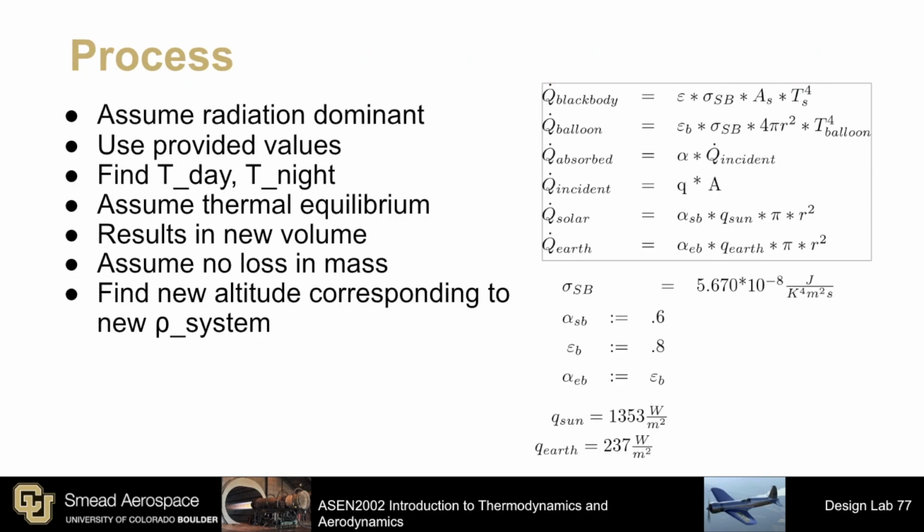Now you may be thinking that what we are assuming here is a bit counterintuitive, but it's a fair approximation for reality given the primary learning objectives of this assignment. More specifically, it isn't intuitive to think that the balloon will stay completely stationary until it is fully heated and then immediately go up to a new altitude. The real system would heat up a little bit, which would result in a larger displaced volume, go to a new altitude based on the new density, heat up a bit more as it expands, resulting in a new density, and then going to a new altitude, etc., etc.